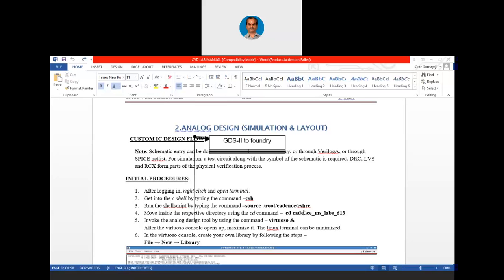So what we have done is, we have kept all those commands in a batch file. That batch file, we have named it as CSHRC. Sometimes we call it as cshrc.main also. Now, whenever that particular batch file is invoked, the commands which are there in the batch file are going to be executed immediately so that Cadence tool will be executed. That is the idea there.